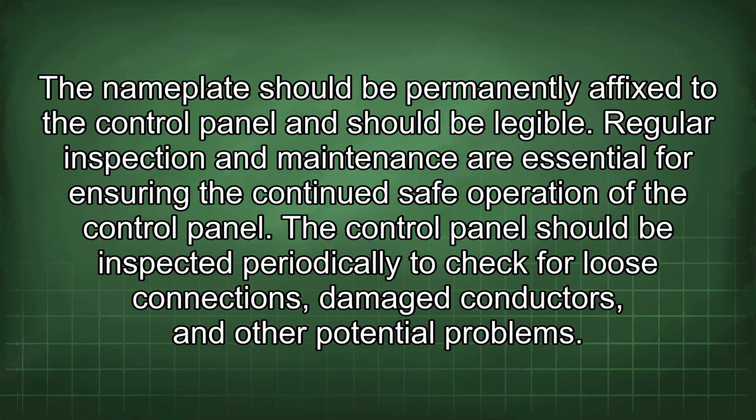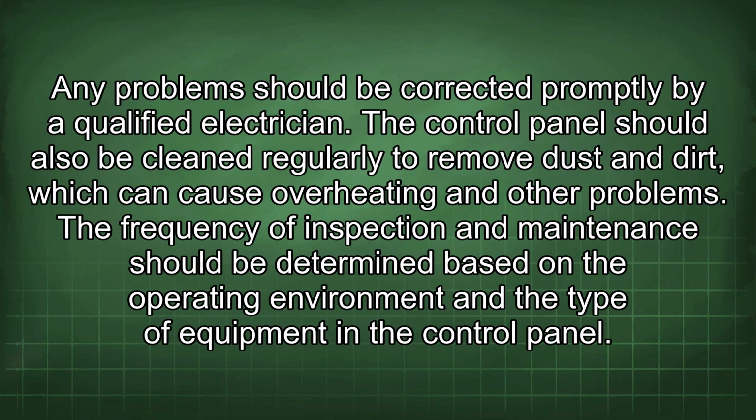The control panel should be inspected periodically to check for loose connections, damaged conductors, and other potential problems. Any problems should be corrected promptly by a qualified electrician. The control panel should also be cleaned regularly to remove dust and dirt, which can cause overheating and other problems. The frequency of inspection and maintenance should be determined based on the operating environment and the type of equipment in